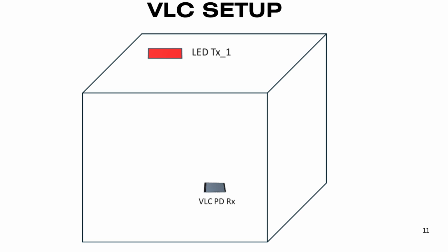The FOV is the widest angle over which the receiver can collect light. Although it can be as large as 90 degrees, the FOV is often optimized to meet specific system requirements. Tuning the FOV helps the receiver concentrate on the intended signal path and reject unwanted background light.